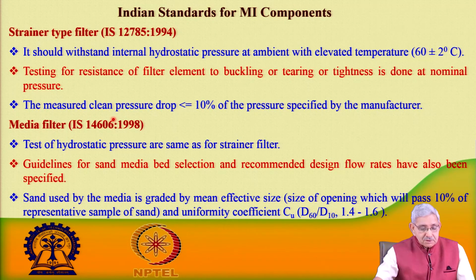So, it should undergo these tests, and the clean pressure drop should be less than 10% of the pressure prescribed by the manufacturer. Media filter, whatever the strainer has, it should follow, and then there is a guideline for setting the media for the preparation of the bed. And the sand which is used should be graded sand, and it will pass 10% of the sample of the sand.